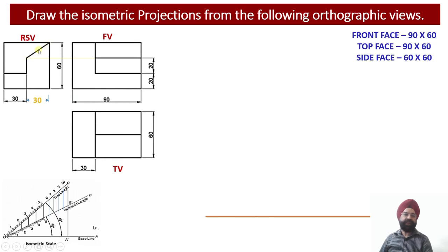So what are the dimensions of this inclined surface? We can check. The length of this surface is 30 millimeter and this is the hypotenuse basically, right? And what is the depth of this particular inclined segment? This is equal to 20 millimeter. How did I evaluate this 20? Because the base ring is 20, the intermediate flat portion is also 20, and then this is the slant portion. So if I work out this length, this distance is 30, this distance is 20, so this will automatically be the hypotenuse of this particular right angle triangle. Based upon construction, we are going to work it out.